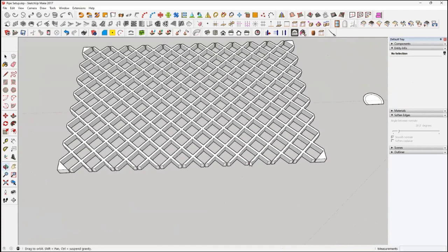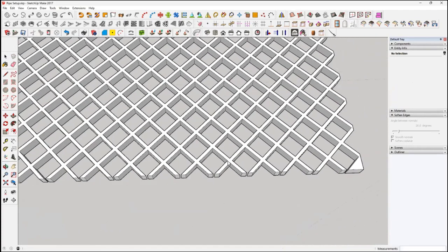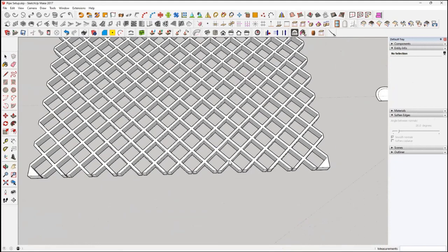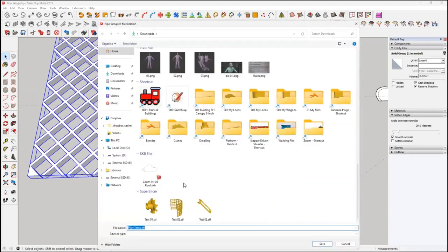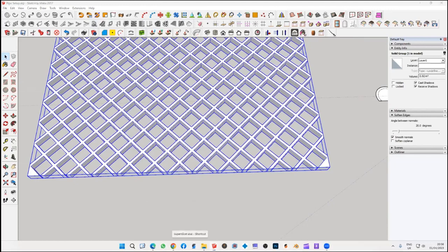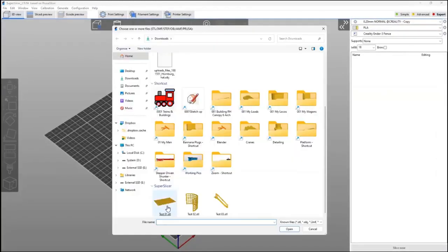FDM print these as well, because sometimes it's better to go for a thickness of 0.4, which is one nozzle width. So you get nice fine lines. If you go at 0.6, I think it does two lines, so it's not so neat. But if you did want a nice thin grill, go 0.4. We'll see what it's like. Let's put this in export. We'll have a look and see what it comes out like. What size is it? And that's our grill.